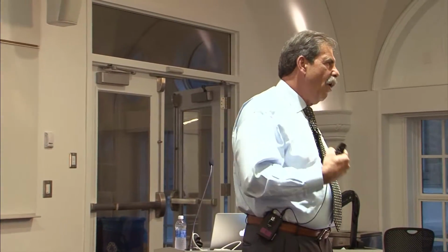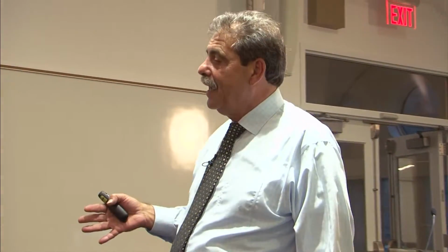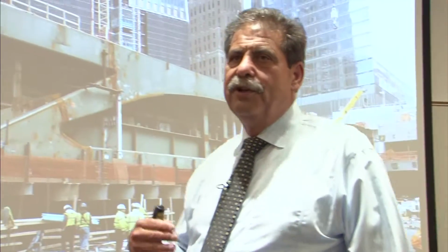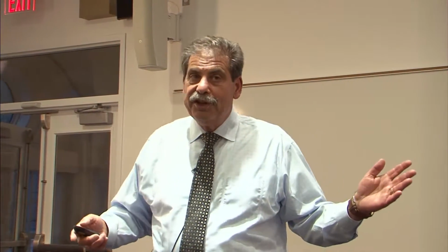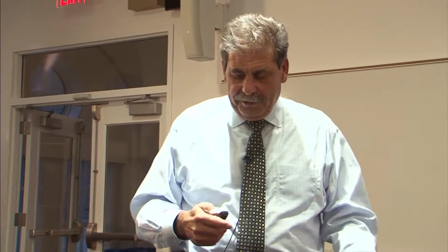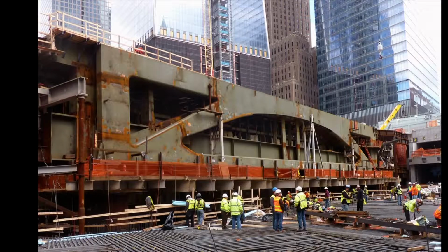Another challenge. How do you create a pedestrian environment below grade that offers some of the awareness and understanding issues of wayfinding in a major transportation facility that's going to deal with 250,000 people a day and not follow the typical New York City subway model, which is a column every 5 feet? So we built 3 bridges in the ground. And you have to understand, this is a bridge spanning, as you see, some 210 plus feet. It's actually a 2-level bridge, because the lower level, that's the subway, and that's actually a station of the subway on the site. And then above, that's the street up there.